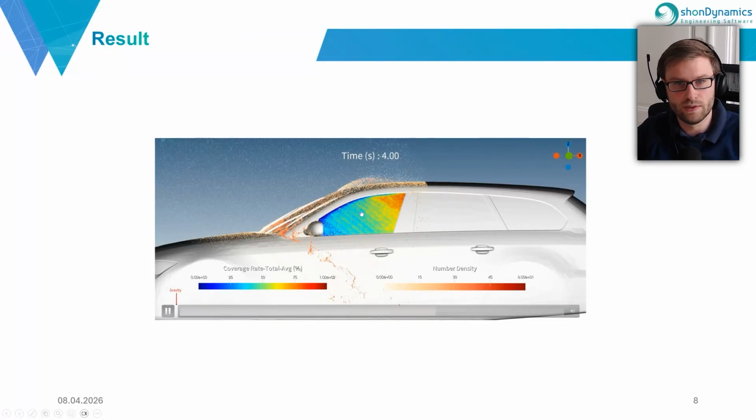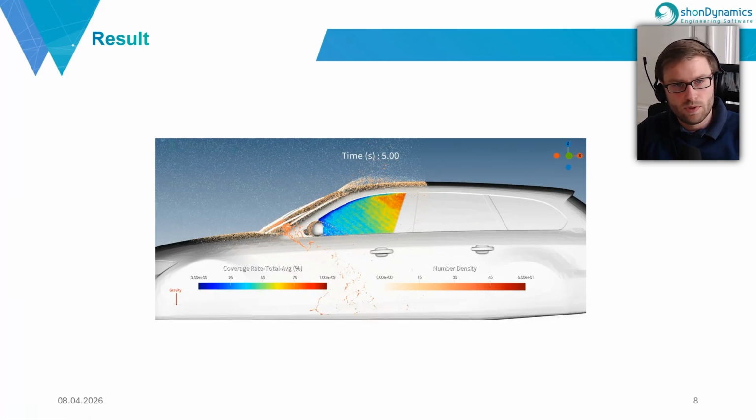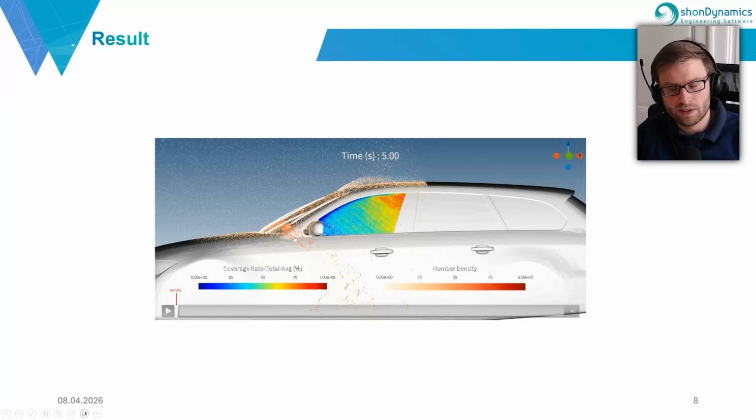So this is again our multi-body results, and this would be our final simulation result with different kinds of post-processing options. For the water, I always used the number density as the variable. The number density is a value for how many neighbors a particle has, and this means, in the other direction, how many chunks of fluid are at one point.